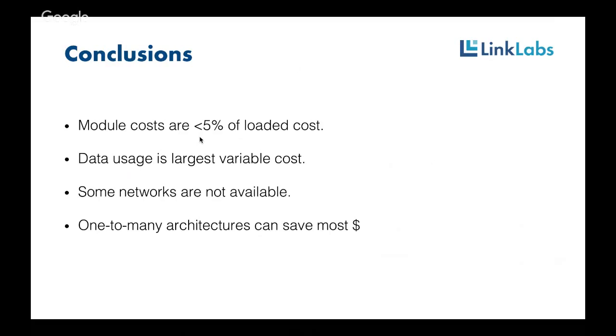Another conclusion, some networks are not available everywhere. Sigfox and LoRaWAN are very interesting, innovative technologies, but they don't exist everywhere. So you can't use them for a lot of applications. And don't believe all the hype and press releases. Try out the technology where you want your device to work, in buildings, in cities, etc.